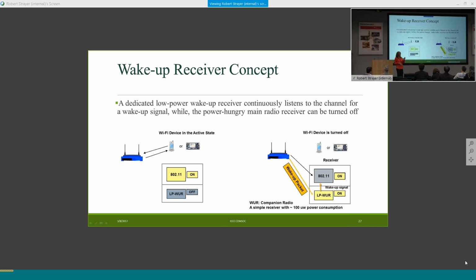Because what you're actually asking is, Wi-Fi has a mesh network. It's 11s actually, another alphabet for mesh network, but it's not implemented. And 11s is not very well defined. So today's Wi-Fi doesn't have mesh, so it doesn't make sense for the wake-up receiver, which is a companion of Wi-Fi, to have that capability, but it can be used with ZigBee.